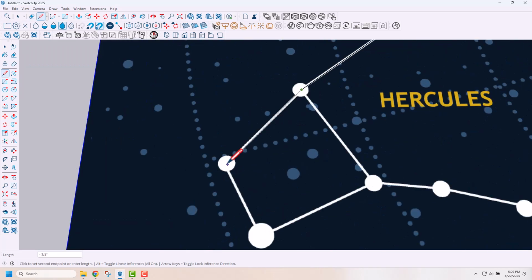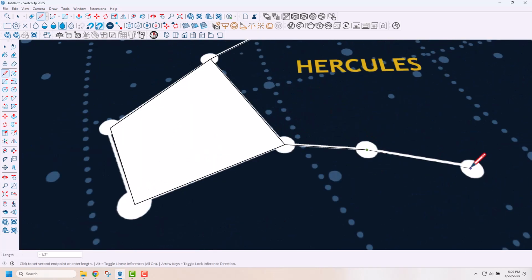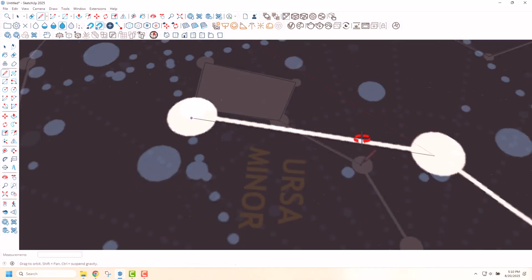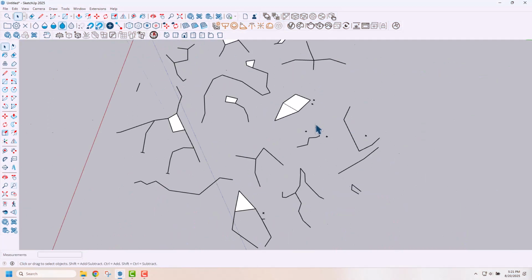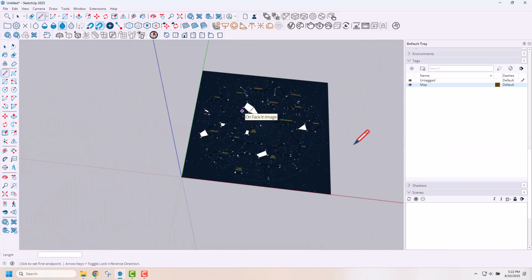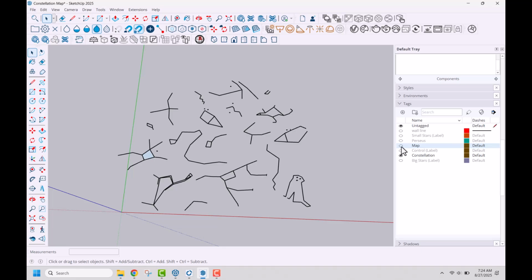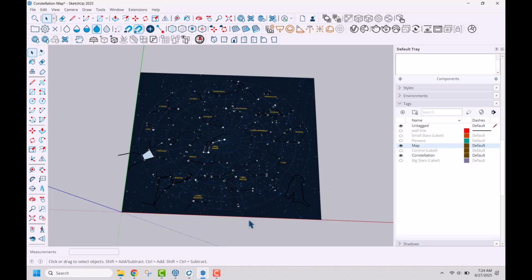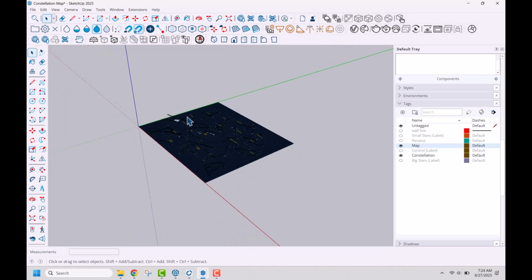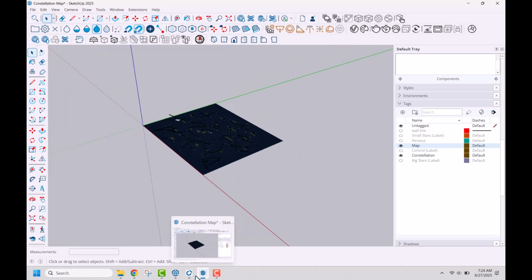This will help me create an actual CAD file, so we'll speed through a lot of this creation. It's just me tracing a bunch of lines using my line tool. Once we do that, we'll finish up, and now we have to make our layout points. I'm going to be using a Trimble Robotic Total Station to lay out all of these points on my ceiling. You can see the CAD file that we finished up there, and I threw my dog in the bottom corner just to make him happy as well.